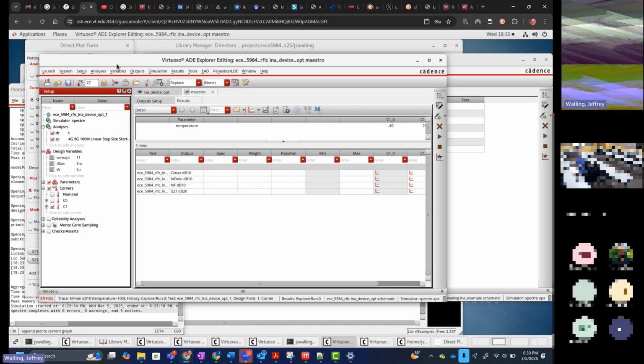Well, I don't think I'd make any kind of qualification on that because ultimately, in order to achieve a certain minimum, you might need to burn more power, right? So if you have a spec, you need to try and achieve that spec without costing too much in other regimes. For instance, you might not need to operate at the optimum current density with a high amount of current. You might be able to lower the amount of current and still achieve a good enough noise figure, for whatever your spec is. So an optimum design is not an over design.